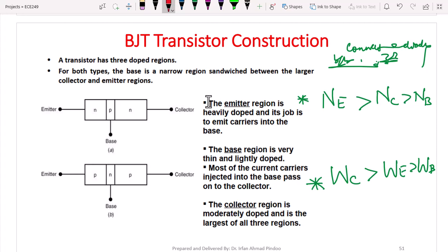So when your transistor is in the working condition, where will the heat be generated? Heat will be generated obviously at the collector only, because we are taking output from there only. All the electrons are coming there only. So that is why we need more surface area, so that we can dissipate away this particular heat, right? That is why its area must be highest, followed by emitter.